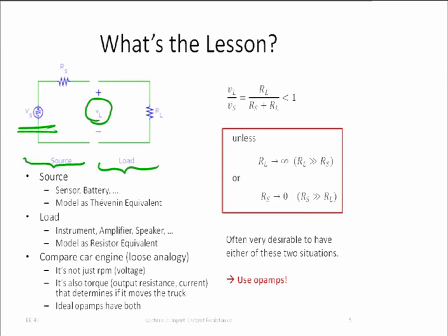Okay, and of the two cases that I showed you, which one implements this? Well, when we had the voltmeter, right? The voltmeter really had an RL that was 10 megohm, that was almost 100 times larger than the 120 k ohm, and so the error was really small, right? Okay, sort of a percent, and that I couldn't see on my graph, right? So that's the first condition.